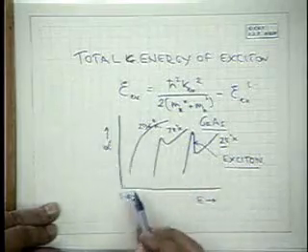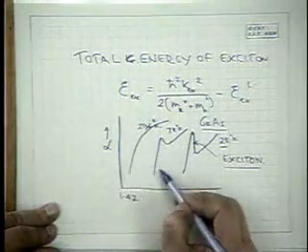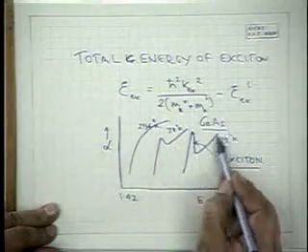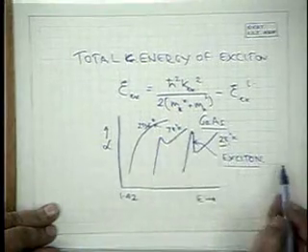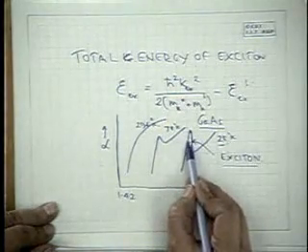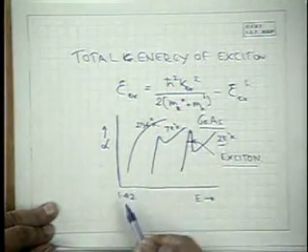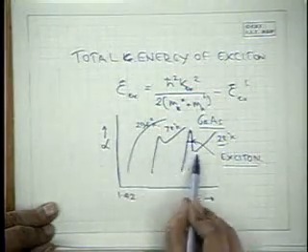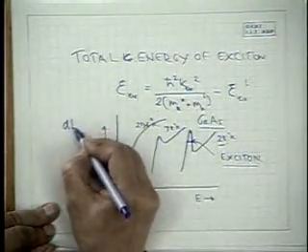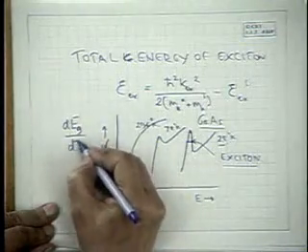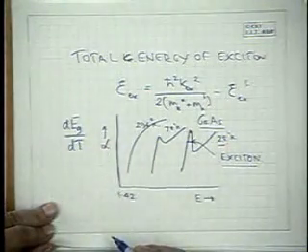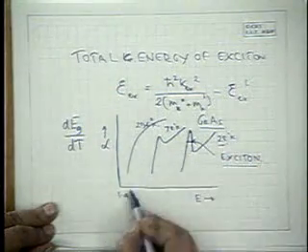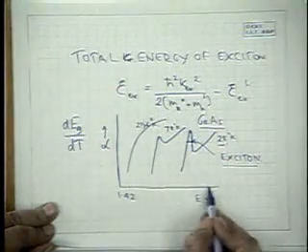As pointed out last time, typical spectra for gallium arsenide, the optical absorption versus energy, give you peaks corresponding to excitonic absorptions at low temperatures, 21 and 78 degrees K. The peaks are much sharper at lower temperature, and the general shift is due to the shift of energy with temperature. As the temperature decreases, the band gap increases.